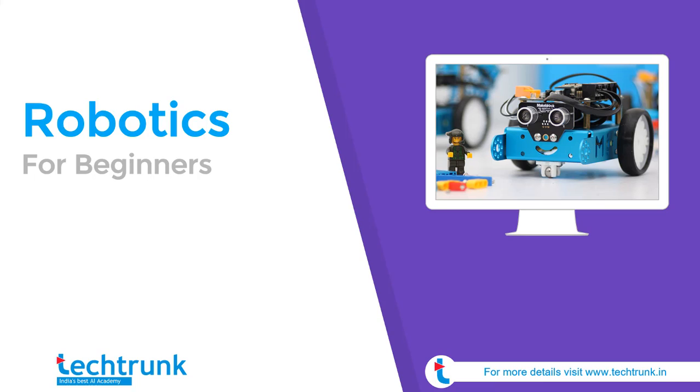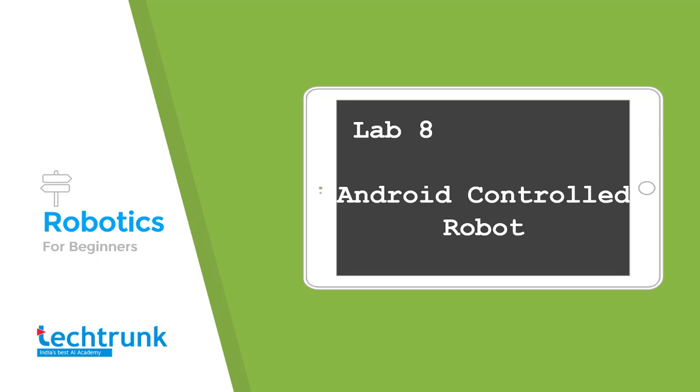Hello everyone and welcome to this video of the course Robotics. In this video we are going to work on an example of an Android control robot, using the technique that we have seen in the PC control robot of serial communication on the same UART of Arduino, RX0 and TX0. We are going to connect the HC05 Bluetooth module.